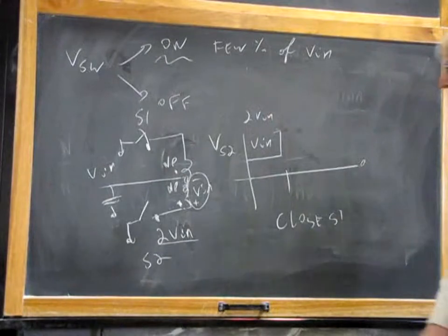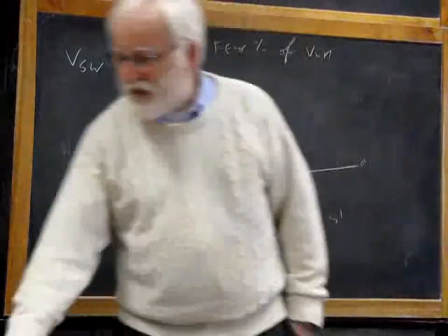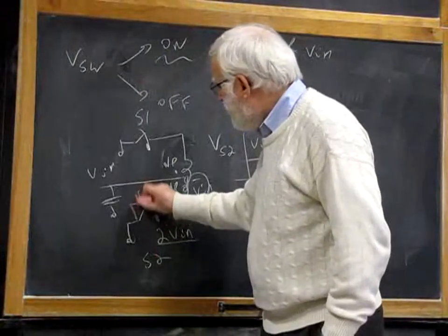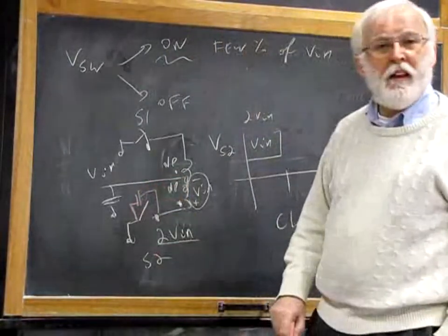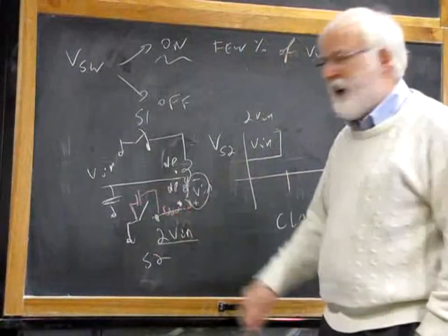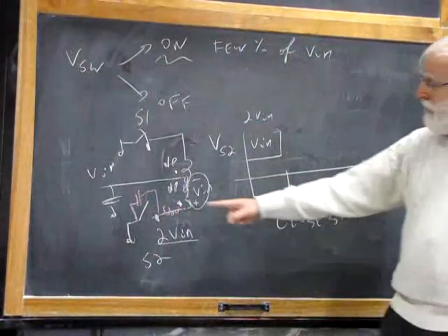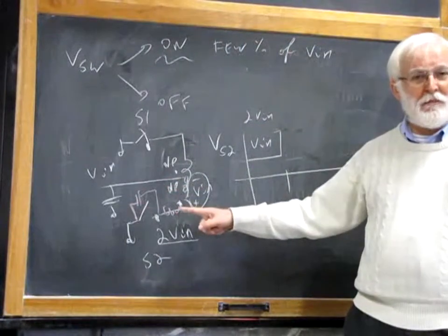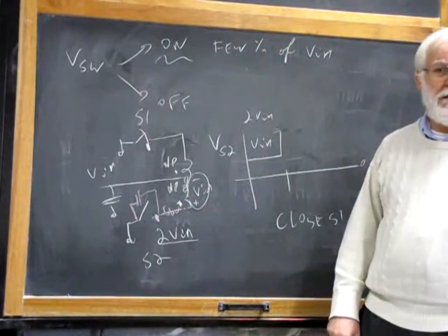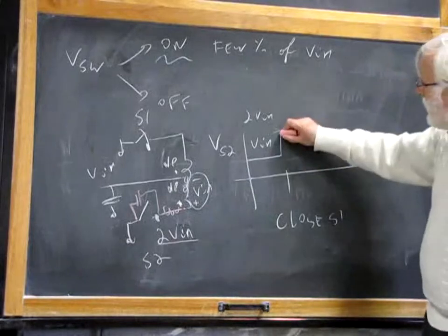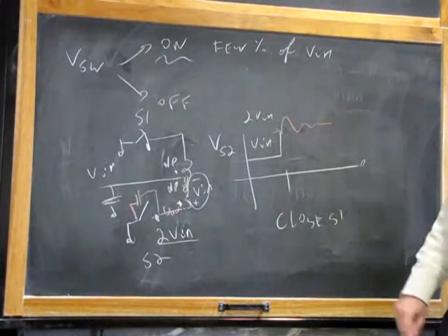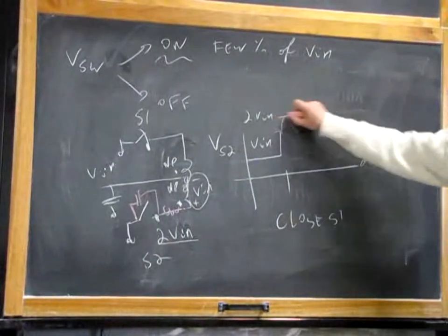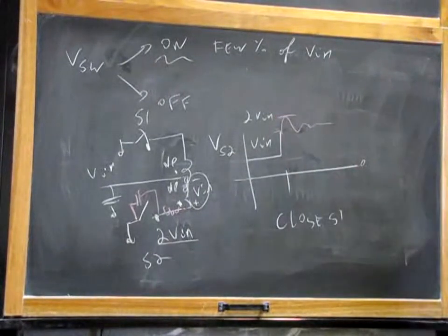You wish, because an open switch is a capacitance. Here you have a parasitic capacitance. Here you have a parasitic inductance, and guess what? You have an LC circuit, and you apply a voltage step to this LC circuit. So what do you get? Resonance. And this will start to resonate like this. So, as usual, you have some extra voltage.